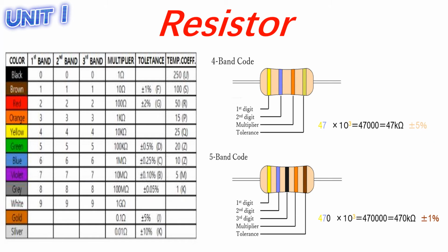So here's another example of your resistors. You have here your 4-band code and then your 5-band code. I want you to pause this video and try to understand and digest the meaning of each code. Also at the end, you have to consider the maximum and the minimum using the tolerance here. This K here means 1,000. So this means 47,000 and this one is 470,000.